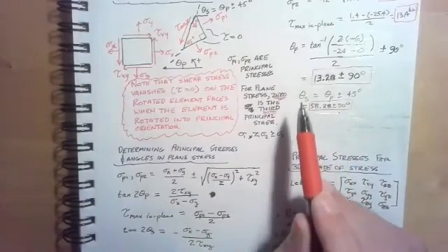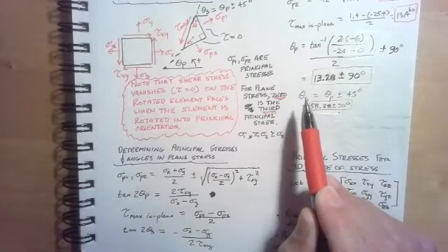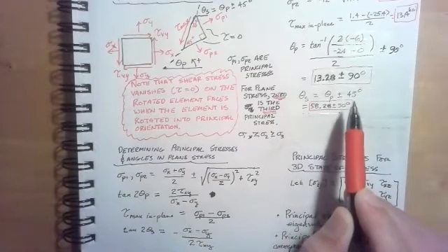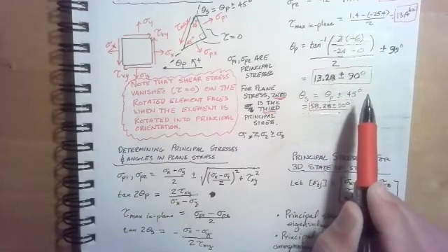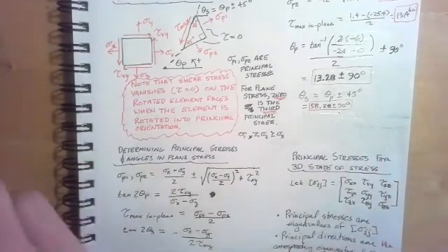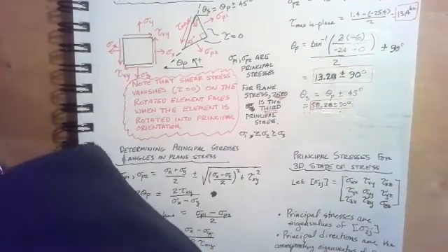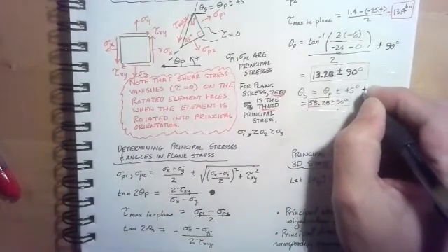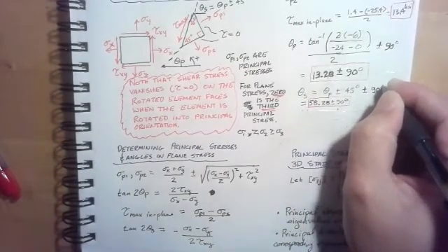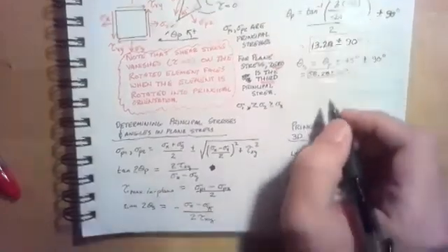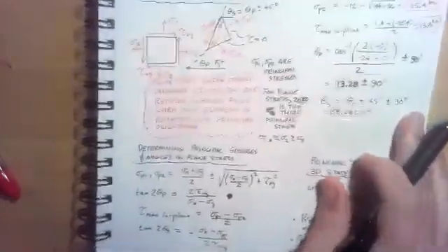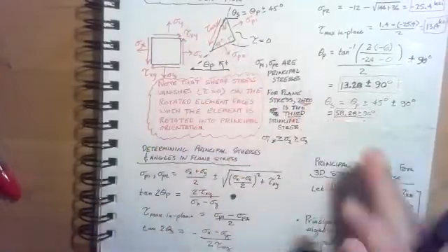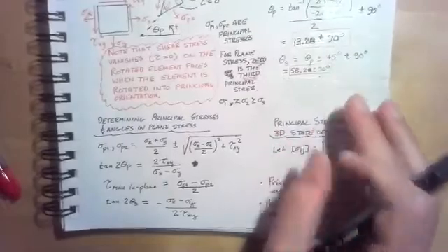And the shear planes, the max shear planes, would happen at an orientation of theta P plus or minus 45 degrees. And then that would also be plus or minus 90 degrees. Because I have another shear plane that would be like this, that would also be a maximal shear plane as well.